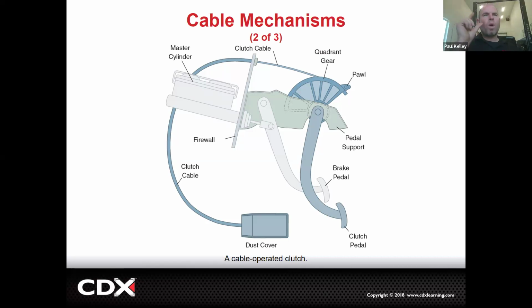As your clutch disc wears, this cable is actually going to get a bit tighter and a bit tighter and a bit tighter. Okay. Backwards from what people think. Like, oh, as the disc wears, the cable's loose, you got to tighten it up. No. As the disc wears, it gets thinner, which means the fork is going to actually pull more and that cable is going to be tighter. So if you were to do a brand new clutch and you were to set this up, you always need a little free play in the cable.